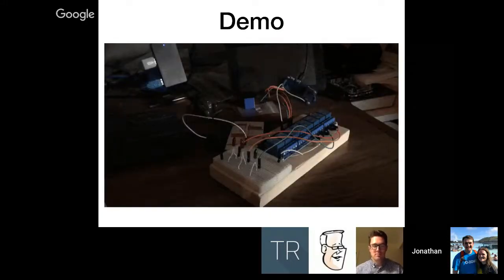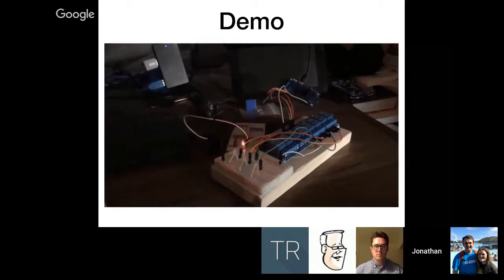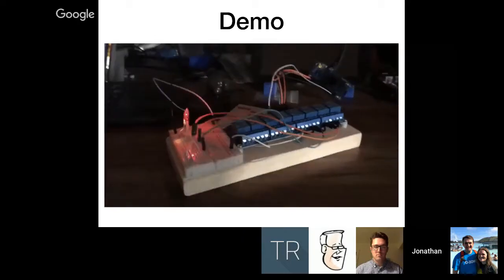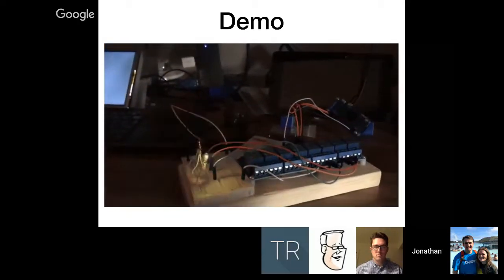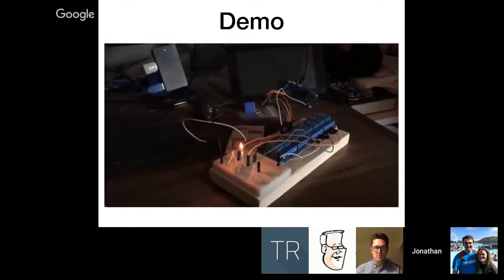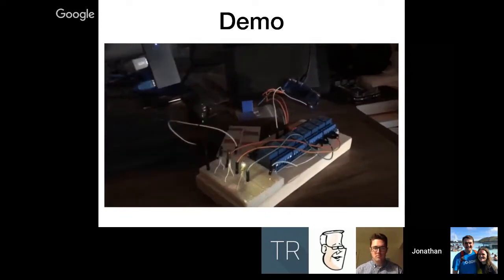Since I got a pack of 2 relays, I mounted one on this wood block with the breadboard and some LEDs, and I made this little test block. Whenever I make a change, I have a bunch of Raspberry Pis, so I'll deploy a dev image to one of those, and I run through a test suite that lights LEDs on a schedule in succession. It'll actually send multiple messages, and I have a little gen server handling those, going through them back to back. That's been really helpful, so I don't have to troubleshoot my code with real sprinklers in my yard.